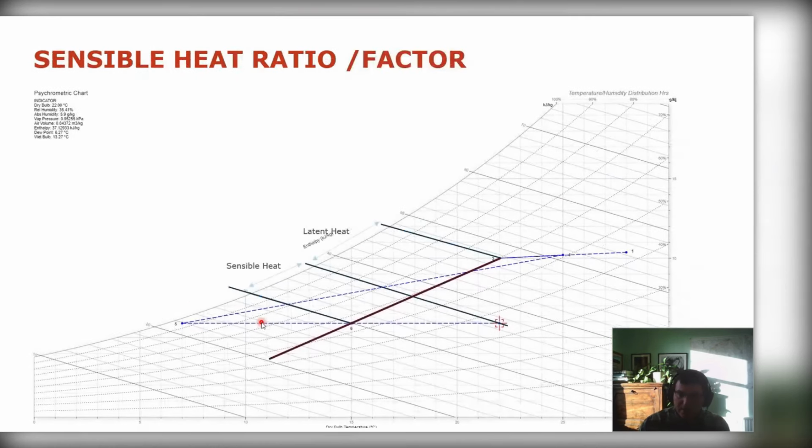However, if you look at this situation, see this line, because there's so much dehumidification required, if you continue straight, you're never going to hit a point where you can use straight off the coil conditions. It's always going to be either not dry enough or too cold. So that's why what we need to do is overshoot and then bring it back to meet the line.